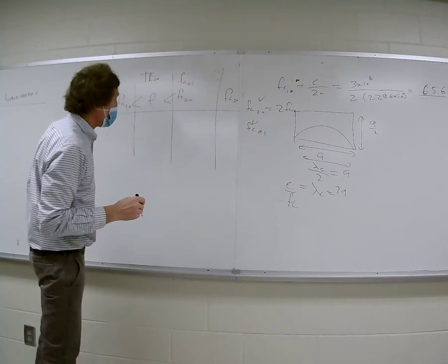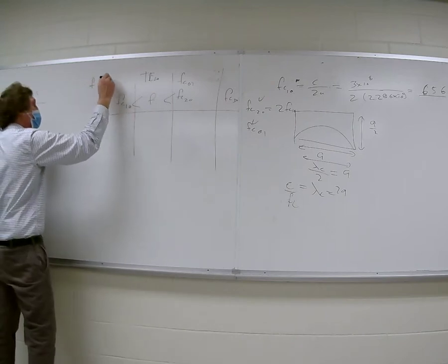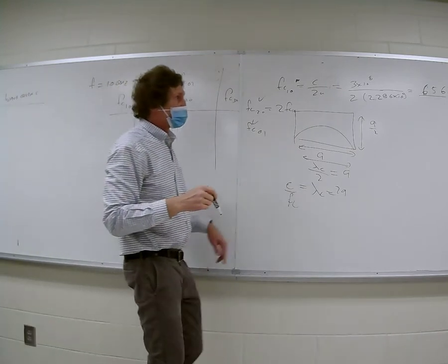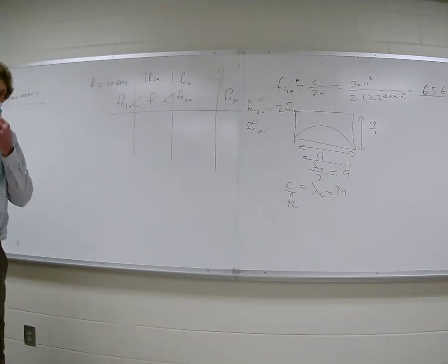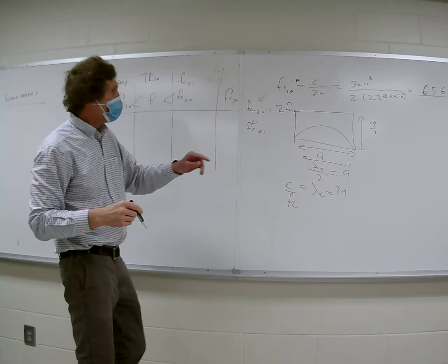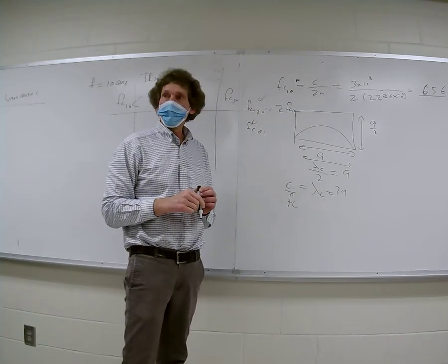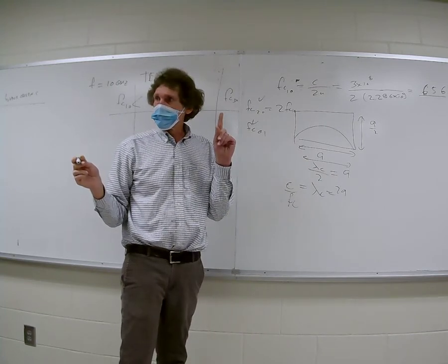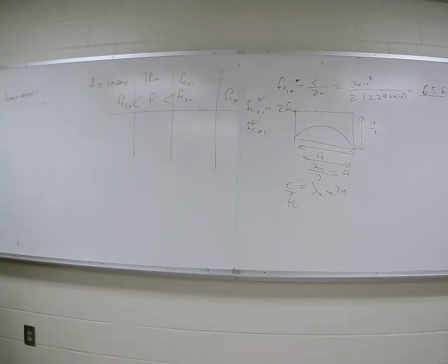What that means is we had an operating frequency for that quiz of F equal to 10 gigahertz, right? Well, 10 gigahertz is greater than 6.56 gigahertz, so we know at least the 10 mode will operate, correct? Right. But it's not greater than 13, whatever it is. I think it's 13.06, something like that. So only the 10 mode operates. That was the whole point of the quiz. All the other modes you don't need to worry about. They're not going to propagate. That was the point, right? And from there, you just go through the permutations.